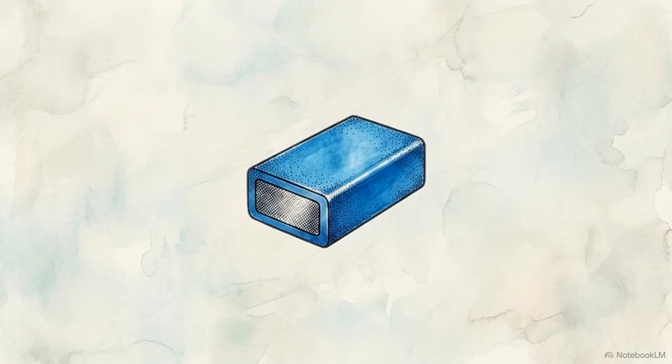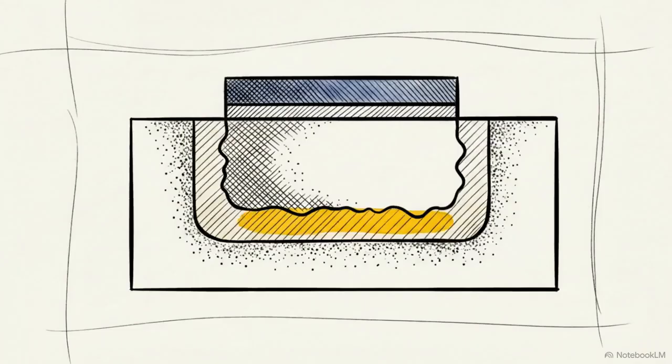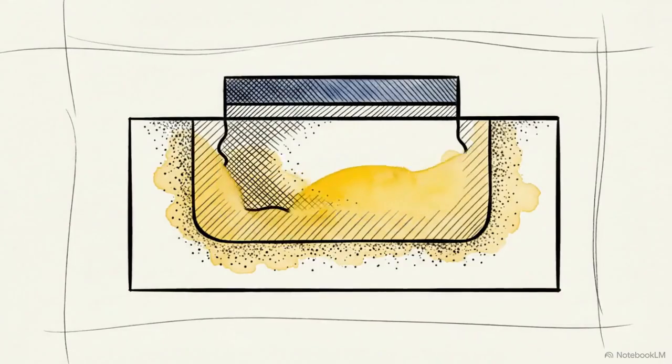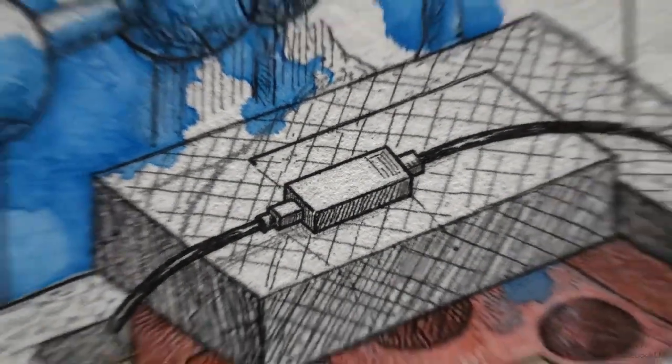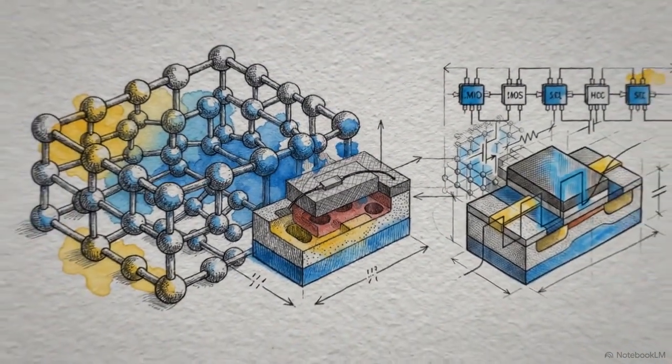Accurate modeling of this effect requires calculating the capacitance across the bottom area of the diffusion as well as the varying perimeter of the sidewalls. Ultimately, this creates a highly nonlinear, unpredictable electrical load that shifts and morphs constantly throughout the entire duration of a logic transition. By combining all of these physical observations, we can finally construct a comprehensive model of the inverter's entire electrical environment.